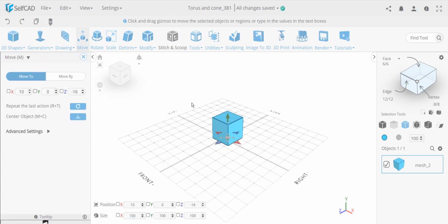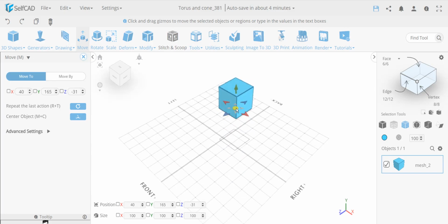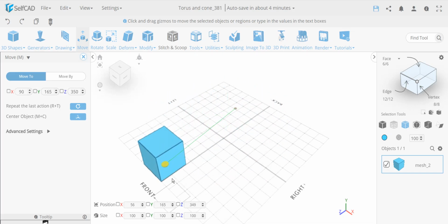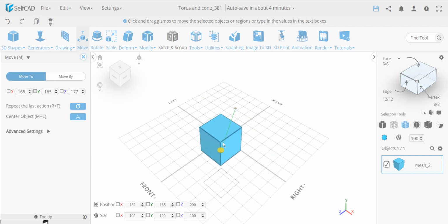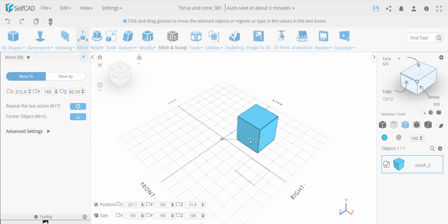Once you open the Move tool, it gives you gizmos, and the gizmos will give you something that you can freely move around. That's the center gizmo by default, and it will give you a fixed axis colored based on the axis. So you can move it in the X direction, which is usually colored red, the blue direction, which is the Z, and the green, which is the Y. So you're moving it in just one direction at a time. Even if we allow you to move it in multiple directions at once, it will be only on one plane, which in this case, the primary plane, is the floor, so you can freely move it onto the floor. You can choose to move it in between two directions by using one of these smaller gizmos.